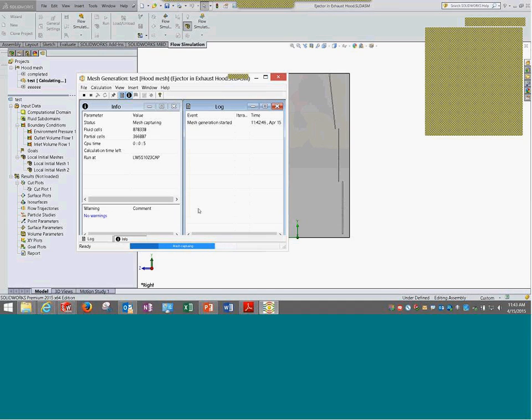We also have an option to give local mesh controls. In the sense, I can create a local dump geometry which can be disabled. However, that geometry can be used to define the number or quality of mesh inside that geometry. So those are the only 3 to 4 options present in the software, and for all practical purposes, the initial mesh option is far stronger. The next best that I can suggest is the geometry option, that is, you select a certain area and tell the software to mesh for that.